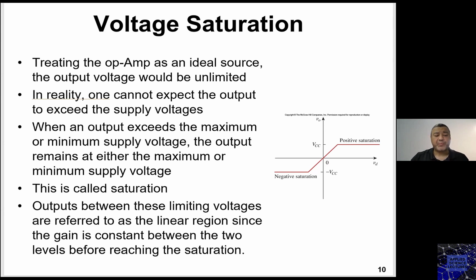And then you are applying a signal at its input. Because the operational amplifier has a high input impedance, it will not draw high current from that signal, which means that it will not load the signal, ending up deteriorating or distorting that signal.